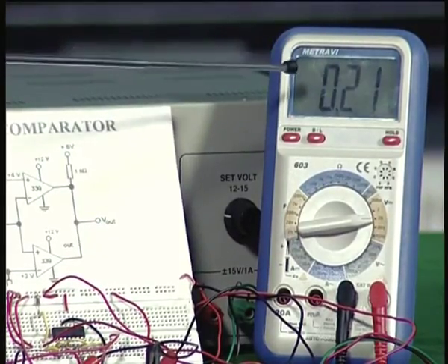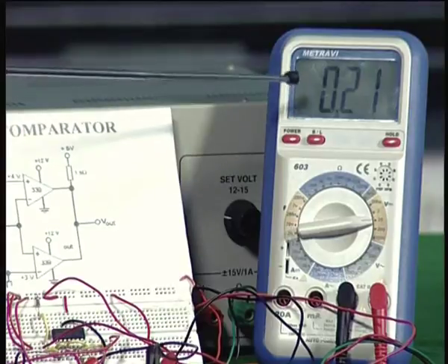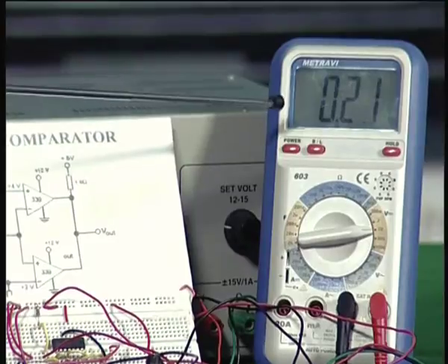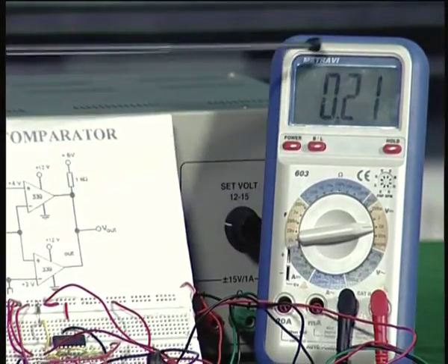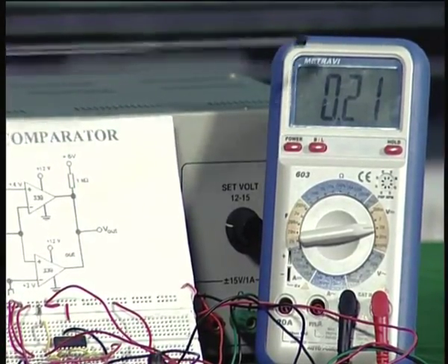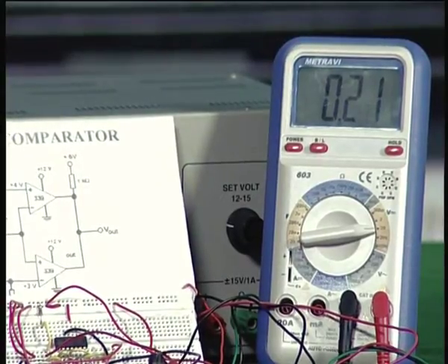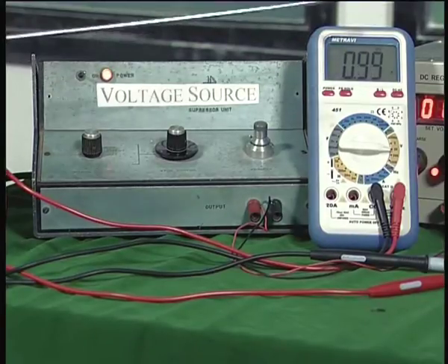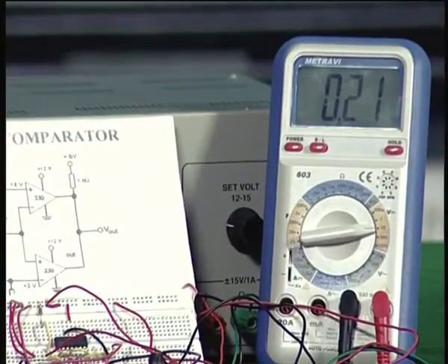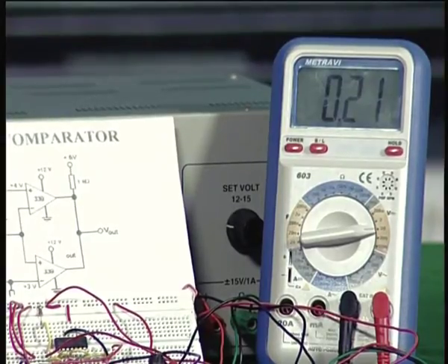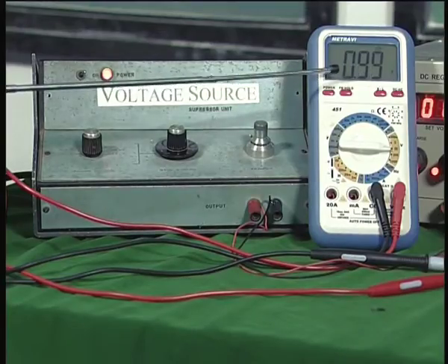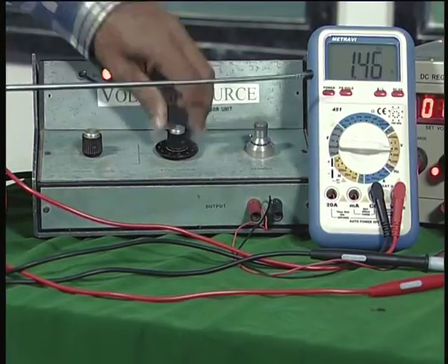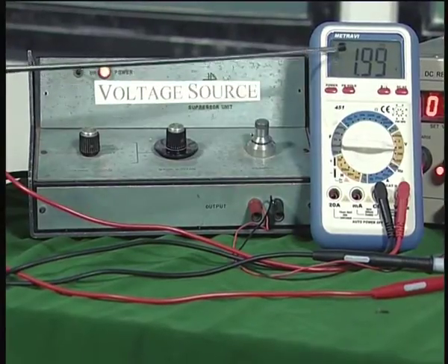Now in this comparator, when my input voltage is between the two thresholds, lower tripping point and upper tripping point, the output will be 5 volts here. So that is what you should try to observe. You should observe what is in the first multimeter on this side, and correspondingly what happens at the other multimeter. So now I am going to vary the input. Right now the input in this multimeter is 0.99, that is 1 volt. So I am going to increase it, so for example 2 volts. Now it is 1.99, nearly 2 volts.